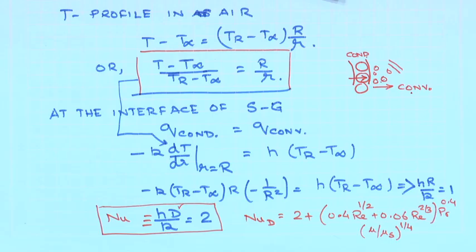So, that is a simple but elegant example of the use of the energy equation to obtain the governing equation, use of appropriate boundary conditions, known temperatures in this case, to obtain the temperature profile in air, and define a Nusselt number for the case when there is no flow of the surrounding air, which you can assume is the limiting case. You can see that it can be expressed as the case where you have convection with 0 velocity.